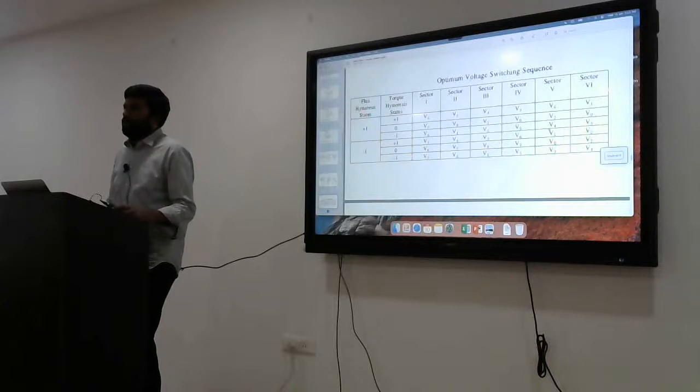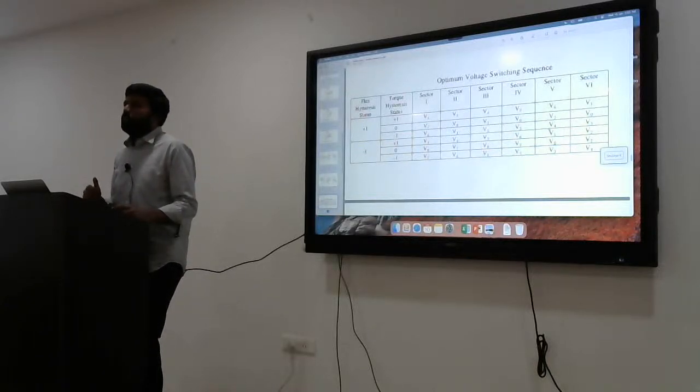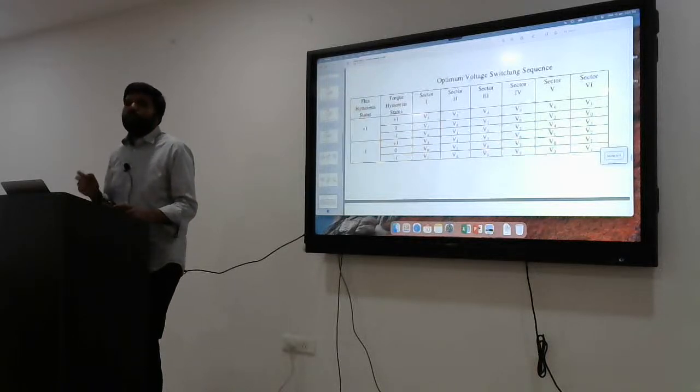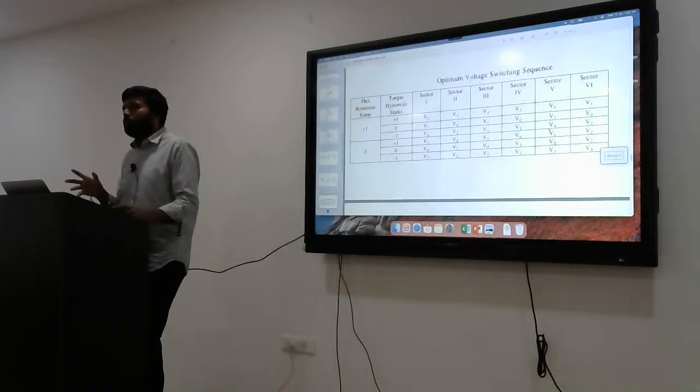If bandwidth is more, tracking of the reference is good. Your actual signal will track its reference very fast if bandwidth is very good. If bandwidth is poor, nothing but the system is lazy. If bandwidth is good, the system is very fast.